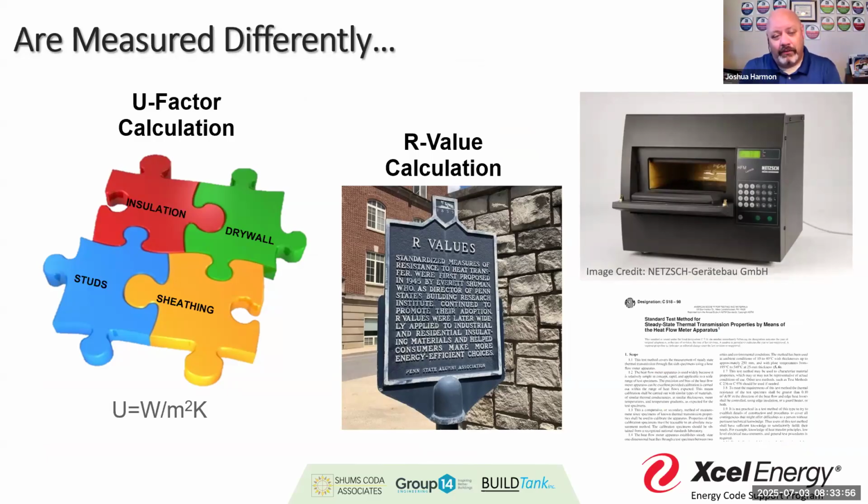And so I said, you either need to choose an alternative R value, an alternative material, or look at the U factor for the assembly, because you may have enough in the assembly to compare it to the U factor and still get compliance. Remember, the R value is a very rudimentary, singular component evaluation.